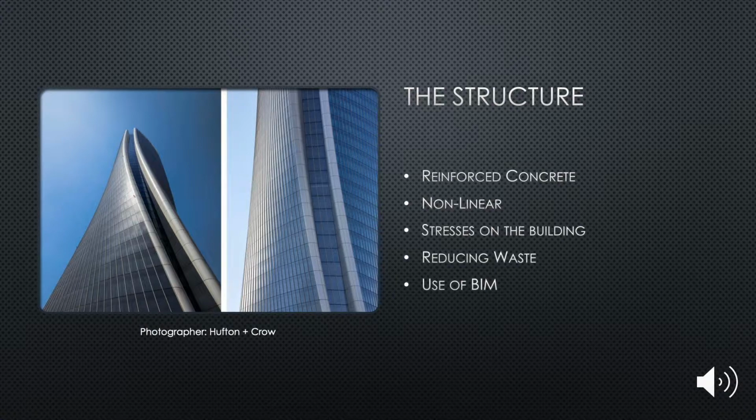As concrete is a non-linear material and the structure will deform during and after the construction, it makes it much more difficult. Due to this, it was imperative that they understood how the internal forces and stresses would change within the structure to allow for the facade, internal elements and installations to be designed to strict tolerances and without any waste.